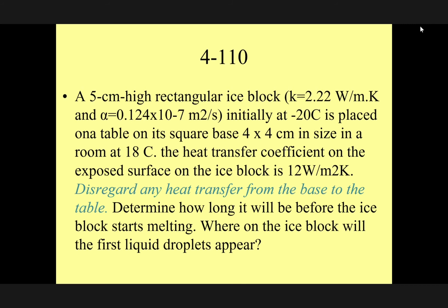Therefore, you have a block of ice on a plate on the surface, and this is heat transferring to the air. That's exactly what we're trying to do. Now, the room temperature is 18 degrees. The convective heat transfer coefficient between ice and air is 12 watt per square meter per degree.